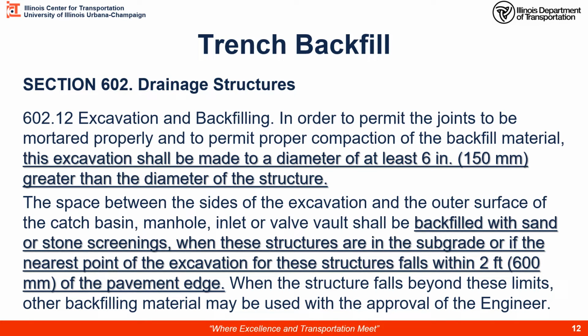When trench backfilling around drainage structures, be aware that under section 602.12, some of this has already been made incidental to that work. For example, if you have a manhole, the excavation shall be made to a diameter of at least 6 inches greater than the diameter of the structure.